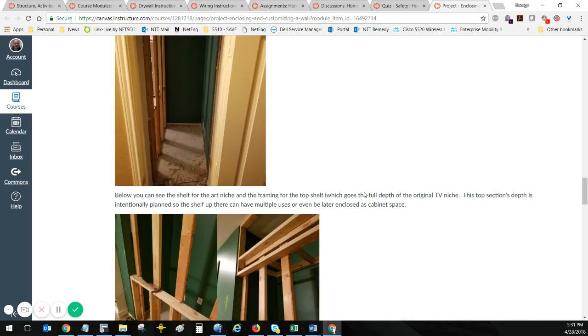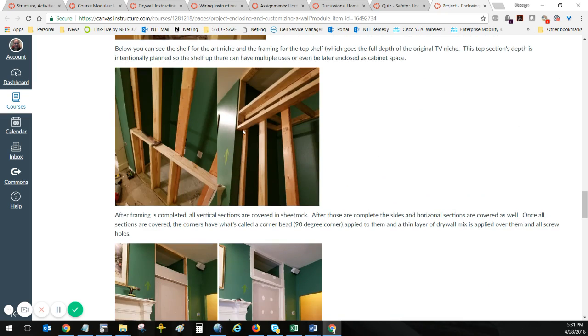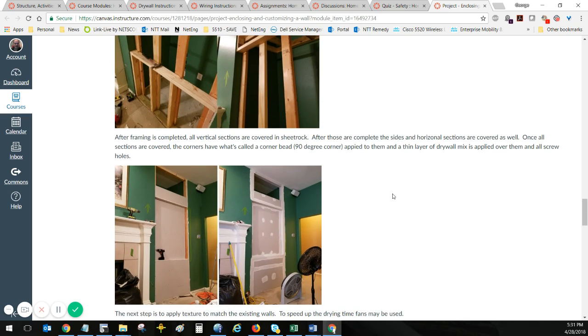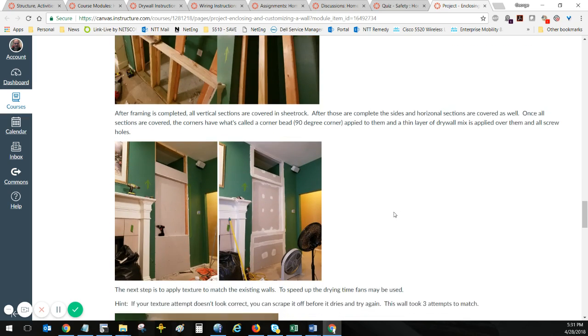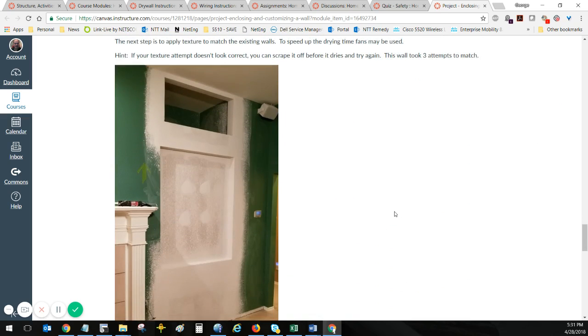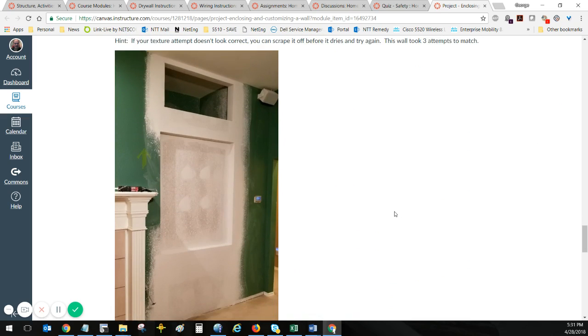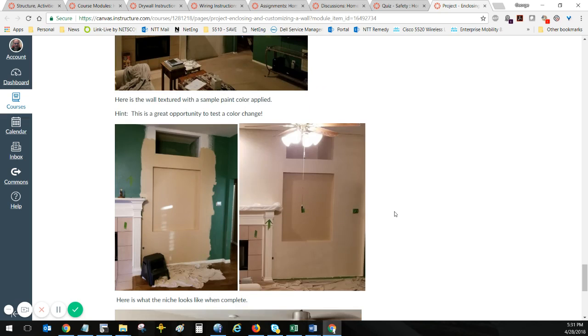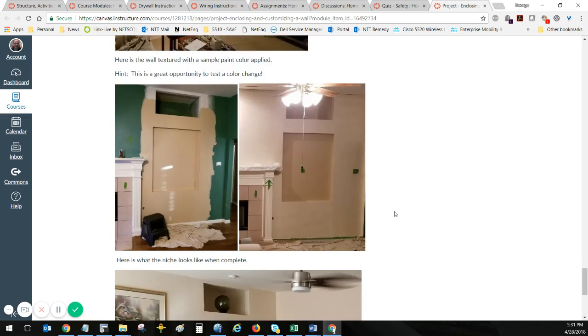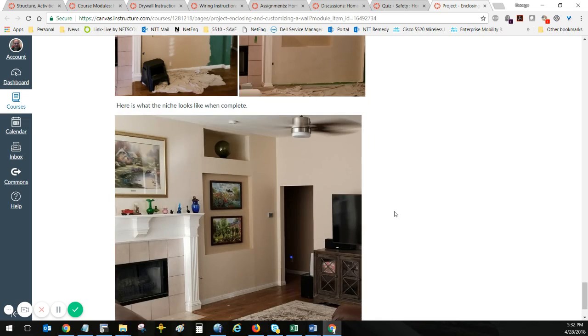Here's the closet side. Make sure that you have your offsets on the wood when you put it on the wall with the proper thickness for the drywall. So left side to right side, any piece of continuous drywall won't have a visible seam or a ripple. Install them, tape it, embed it, blow your texture on the wall, put some primer down, paint the wall, see what it looks like, and voila, you have a completed wall project. And put some art up on the wall.